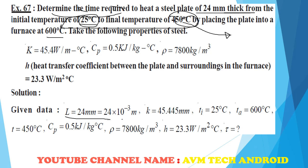The thermal conductivity unit is not mm, it is watt per meter degree Celsius. Initial temperature is 25, surrounding temperature is 600. We want 450 temperature. Cp, the specific heat, is 0.5 kilojoule per kilogram degree Celsius. Density is given, convection heat transfer coefficient value is given. We have to find out tau.